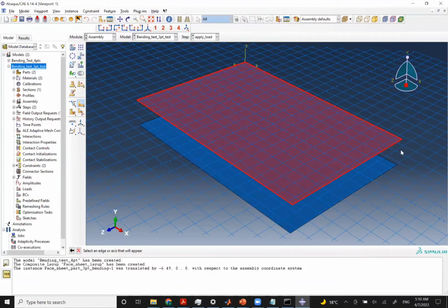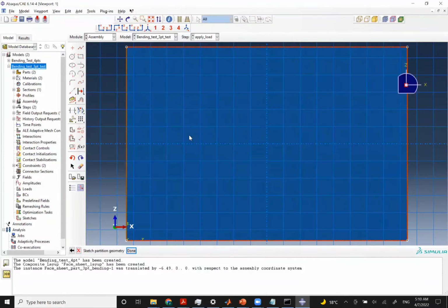And so that's the edge that I clicked, and this is the shape. So basically, I will just create a line, and that line will cut this face. If it is just 2D, as in this case, a line is enough to cut it into two surfaces. And here I will add a dimension.